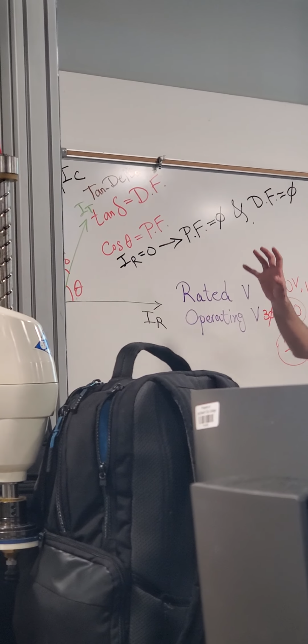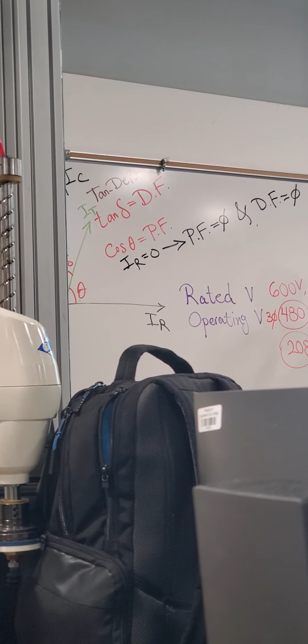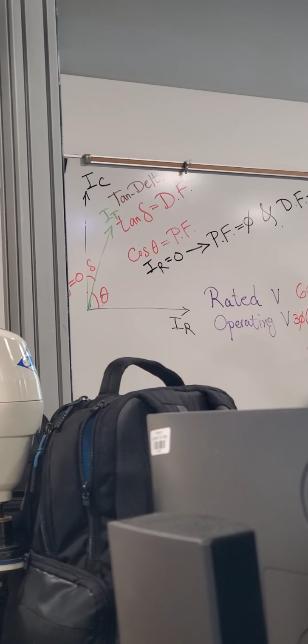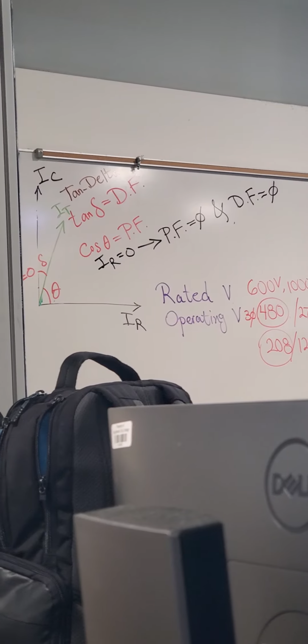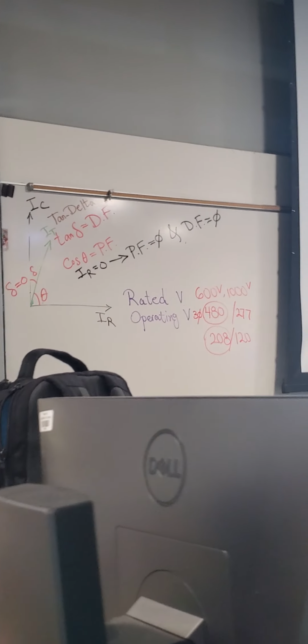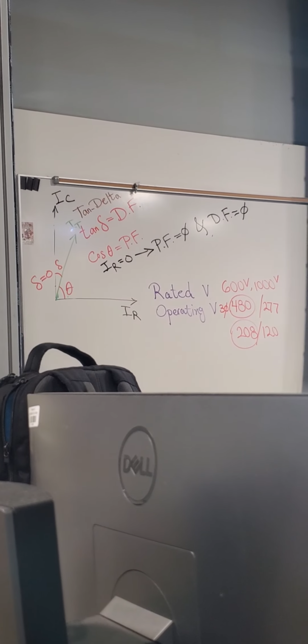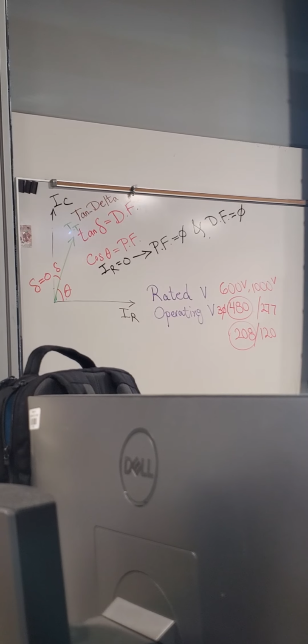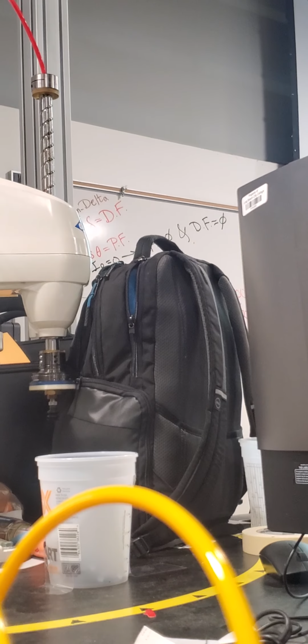Tan delta is a newer kind of testing technology. It's being used mostly on high frequency systems because that gives you more accurate test results. But at 60 Hertz, power factor or tan delta, both.